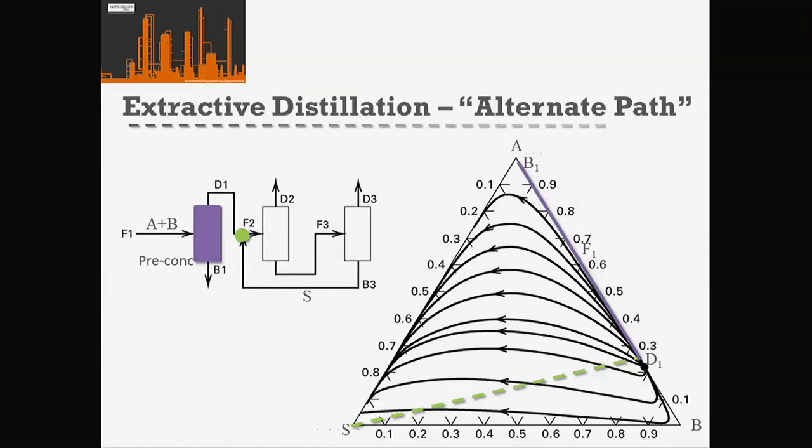So that leaves me with the option of, well, can I get B as our pure component? If I think about coming down here to B, I can see there's this residue curve here that's very close to getting pure B. So I could think about putting a distillate product down here.